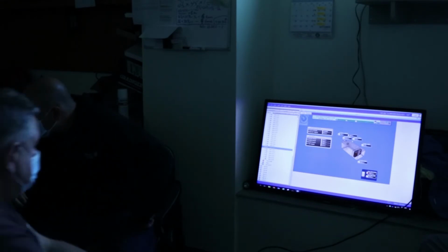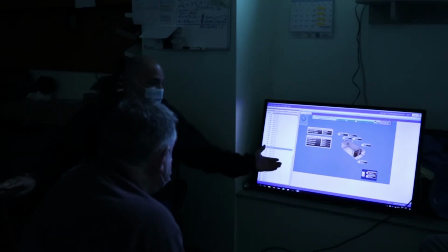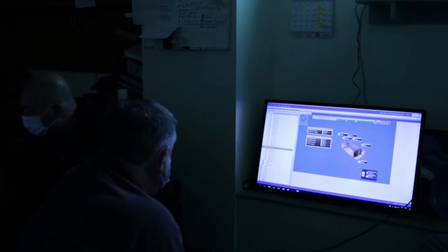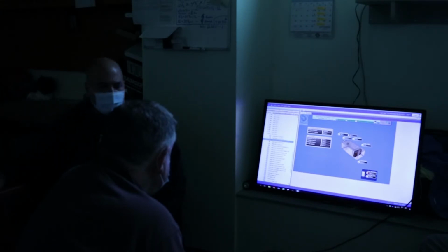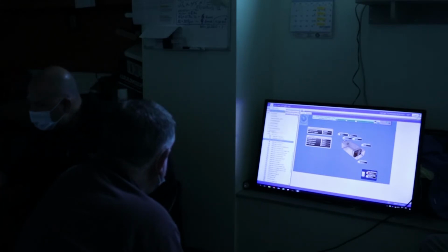Well, this air handler is only doing 65 degrees. This is A27. So 65 degrees is not enough to really cool that, to try and bring that down. But it does look like, we could look at the history, how much history we have on this box. If you highlight it in the tree and you go to view and you go to trend viewer, it'll give you a little bigger picture of it.